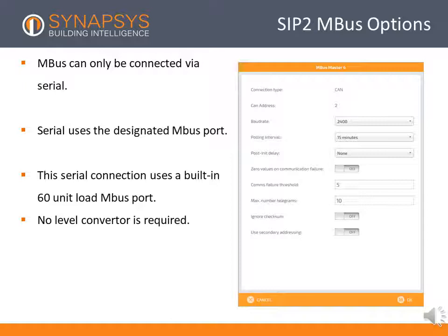Secondary addressing allows for two different ways of addressing M-bus meters on a network. Primary address generally requires manually configuring meters to set an address number between 1 and 250. Secondary addressing automatically defines the address as an 8-digit number. This will generally be the serial number of the meter, meaning all addresses will be unique.